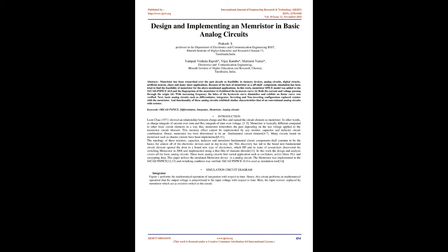for the above-mentioned applications. In this work, a Memristor SPICE model was added to the OrCAD-PSPICE 16.0 and the fingerprints of the Memristor were verified: 1, it exhibited the hysteresis curve; 2, both the current and voltage pass through the origin; 3, with increasing frequency the lobes of the hysteresis curve diminish and it exhibits a linear curve.